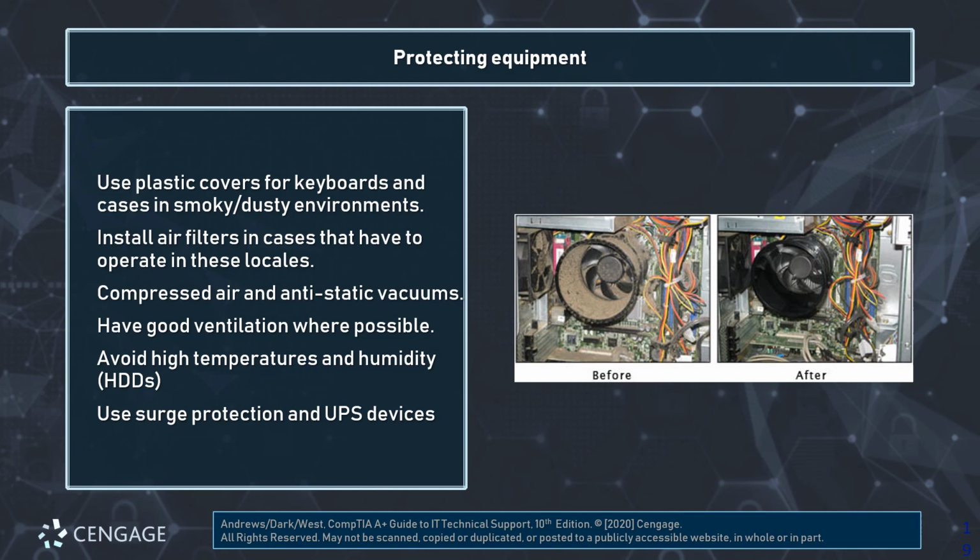Be aware that these can generate static. Anti-static obviously can, but compressed air in certain situations can actually generate potentially more static, which could cause damage, so we always want to be very careful about the environments in which we use that. Have good ventilation where possible, always. Avoid high temperatures and humidity.